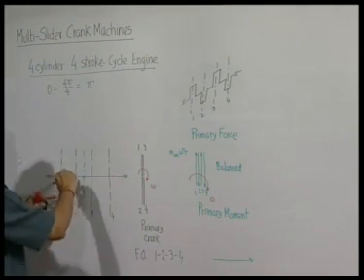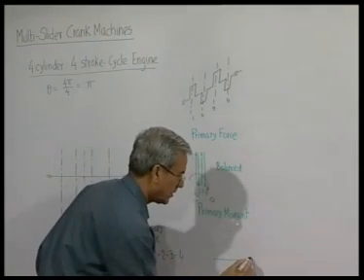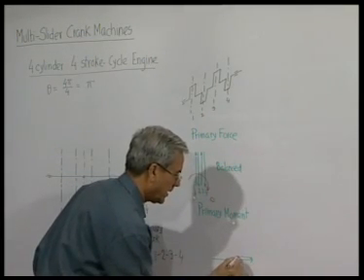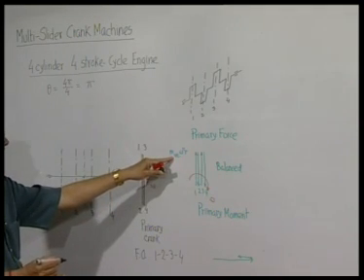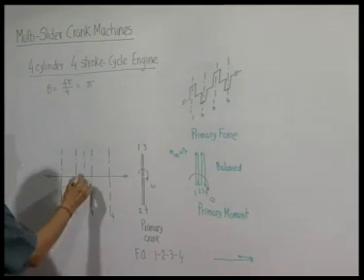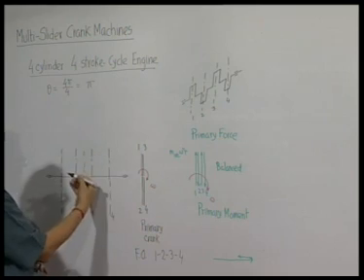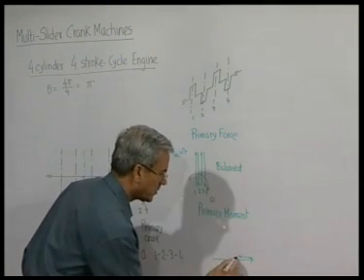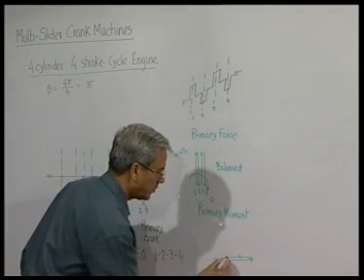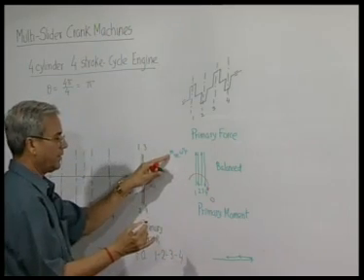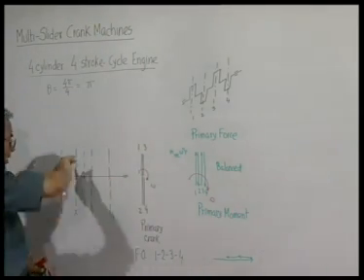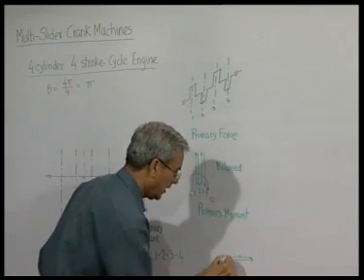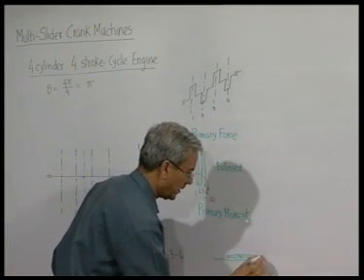So, it produces a moment in this direction and magnitude is this into 0.5 a. Then this one is in this direction. So, it produces again a moment in this direction whose magnitude is again this into 0.5 a. And then finally, 4 produces a moment in this direction by right hand screw rule and comes here.